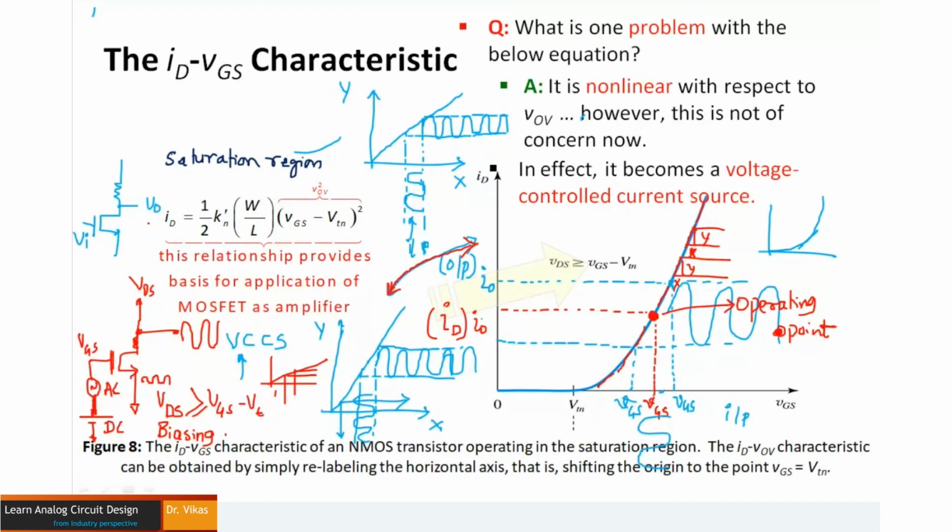So this is the concept of linearity or non-linearity that is really important in any electronic system. But here, because the graph itself was non-linear, I tried to figure out a small region in the graph where it is linear. I don't need the entire graph. I need a small portion where I give that voltage at that point where my graph is linear, so that my entire MOSFET now becomes linear only in that region.